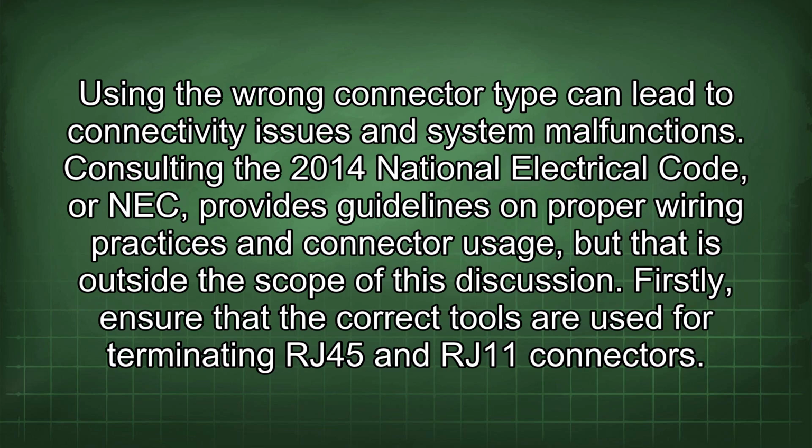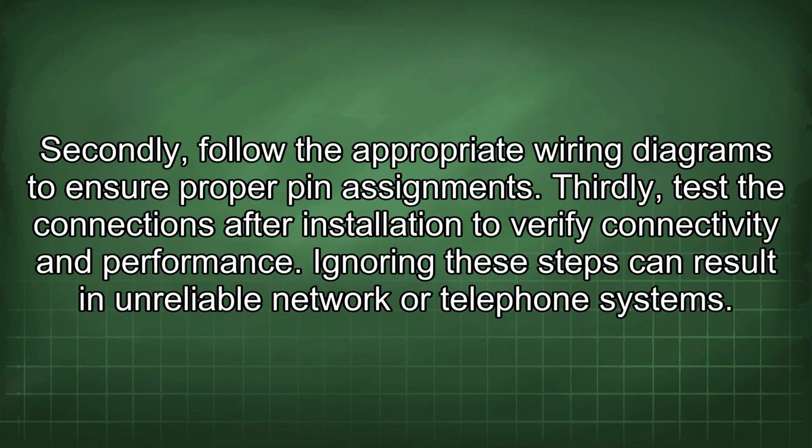Firstly, ensure that the correct tools are used for terminating RJ45 and RJ11 connectors. Secondly, follow the appropriate wiring diagrams to ensure proper pin assignments. Thirdly, test the connections after installation to verify connectivity and performance. Ignoring these steps can result in unreliable network or telephone systems.